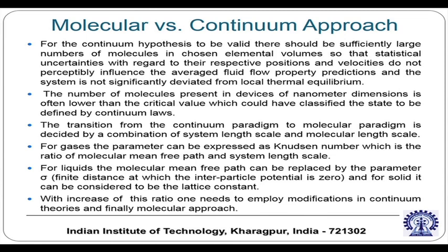To answer the question whether molecular modeling or continuum modeling will work, one has to look into the continuum hypothesis: there should be a sufficiently large number of molecules in the chosen elemental volumes, so that uncertainties with regard to their respective positions and velocities do not result in any appreciable deviation in the prediction of flow properties and fluid properties.